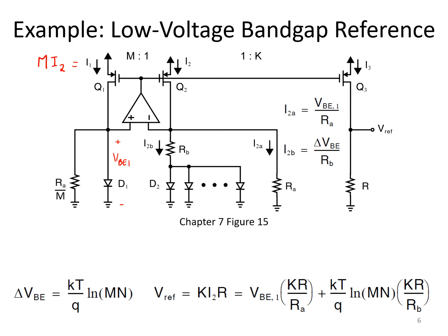And again, the op-amp ensures that very close to the same voltage appears here. So already you can recognize that there are some requirements on the op-amp in order to ensure that the circuit operates properly. For example, it should have relatively low input referred offset voltage, and moreover an input referred offset voltage that's temperature independent to ensure that these two node voltages are matched.